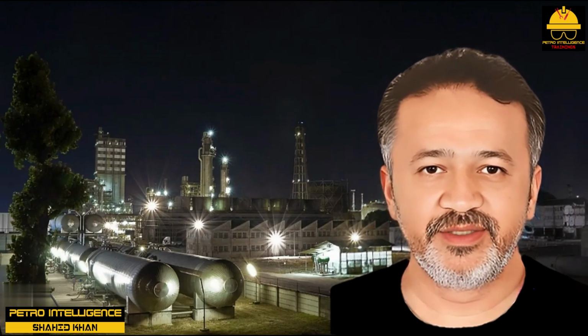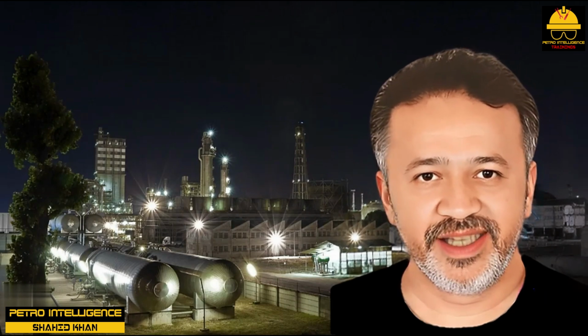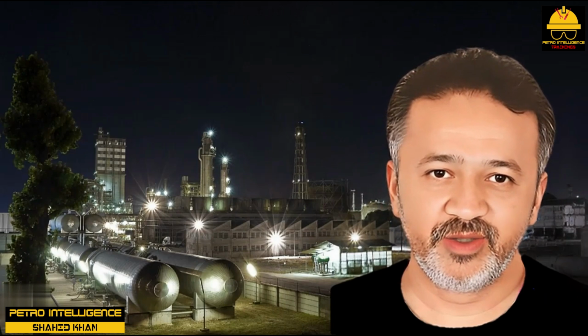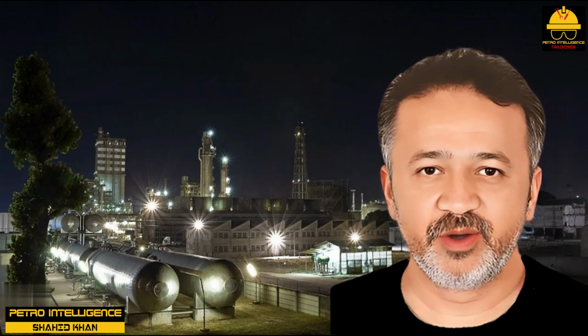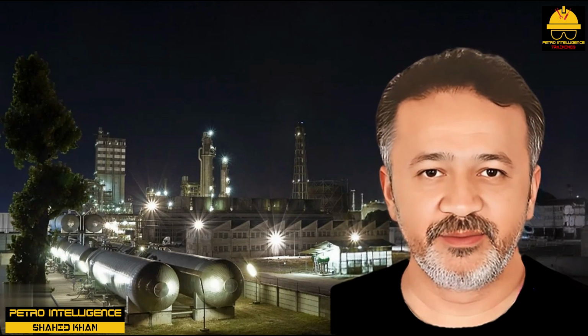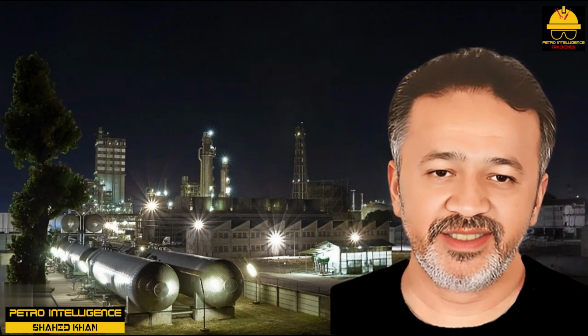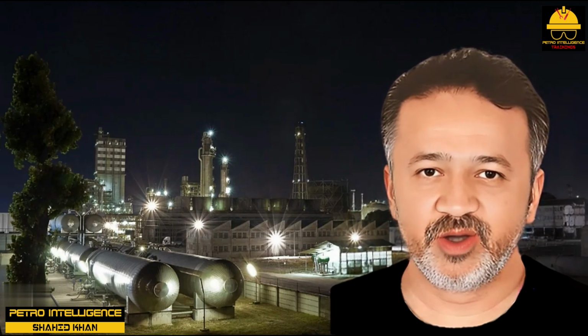Alkylation. This is a very exothermic reaction. Isobutane and light olefins react to form isooctane, a gasoline blending component with a 100 octane. That's where the word octane comes from. Reaction takes place at 50 degrees Fahrenheit, in a liquid phase of either H2SO4 or HF acid.